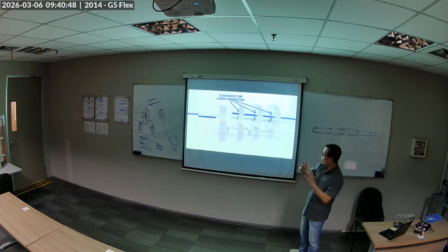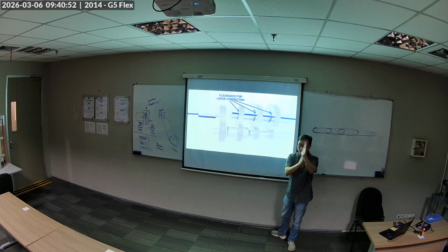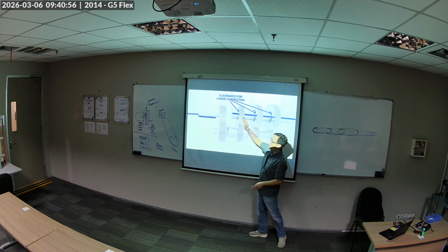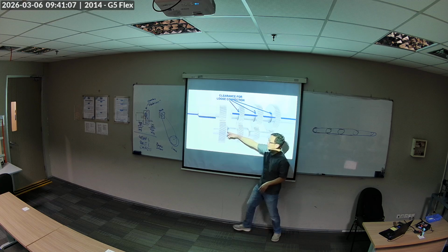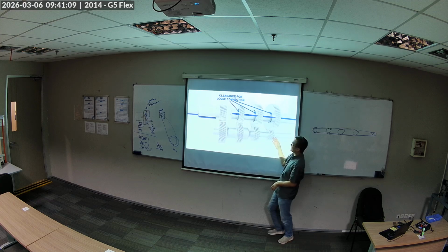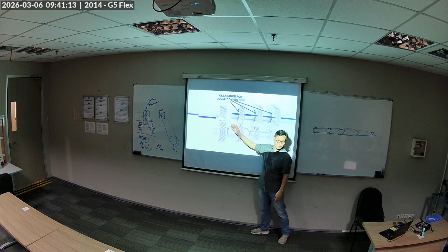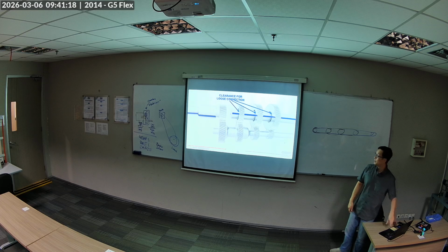So the gears are always connected here. There is no disconnection between the gears. The gears are always connected, but not connected to the output shaft. So if you do not engage the shaft with the gear here, then nothing happens, right? Because the input will rotate along with the counter shaft, but nothing happens here. Okay? So the question then becomes, how do you join them?